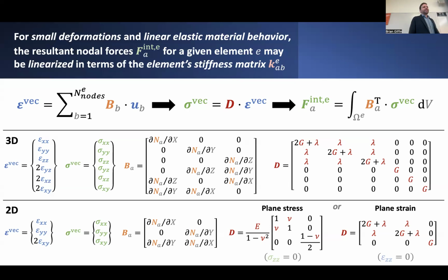It's basically just a matrix filled with possibly some 0 entries or otherwise different values of the gradient of the finite element shape functions plugged into different entries. And this gave us a way of taking vectors of nodal displacements at all the nodes to corresponding values of the strain at certain integration points of interest.